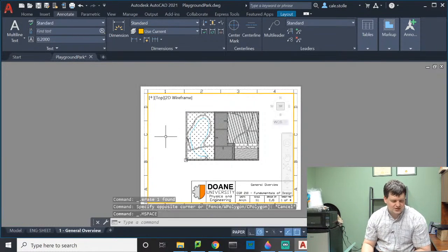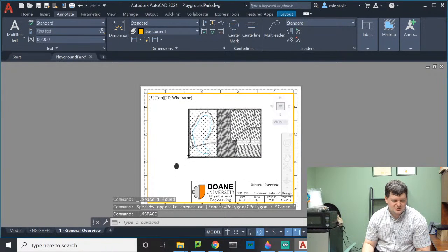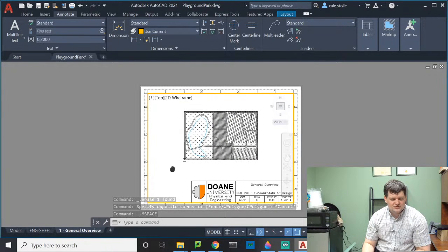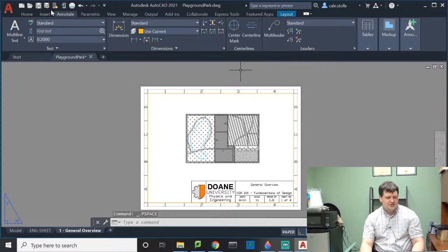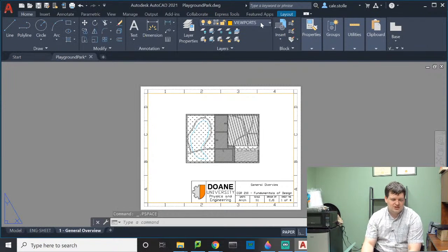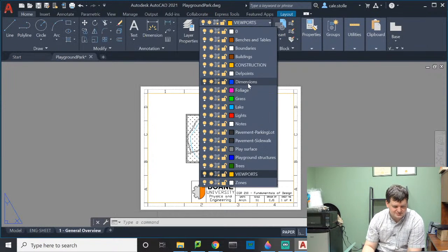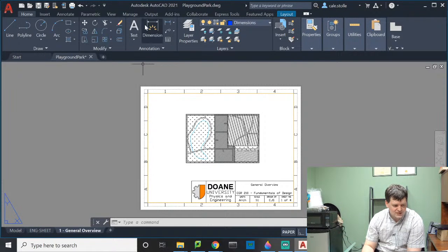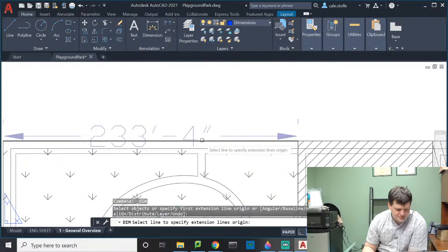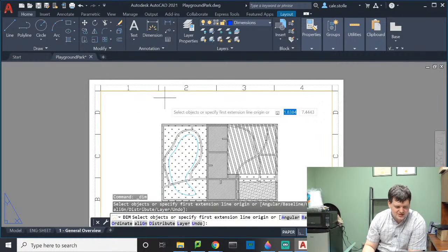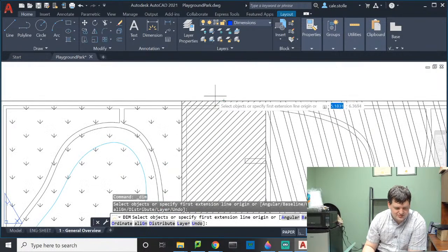So, all right, now I have my dimension, I have my drawing appropriately scaled. I'm going to put this in the center here, come over here, and now I will go to my dimensions layer, and I will actually put in dimensions. Now, first thing I'm going to do is, you'll notice I am in the paper space right now.